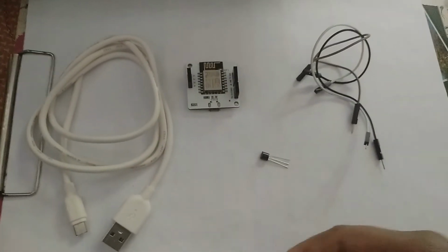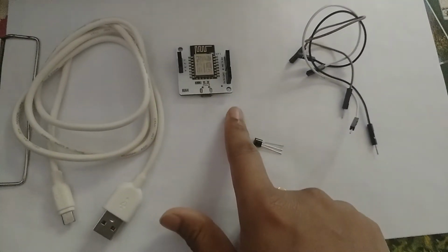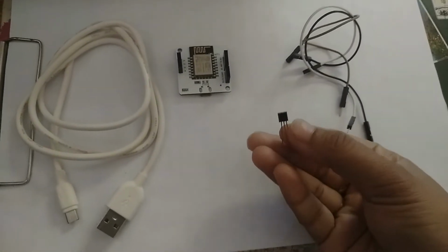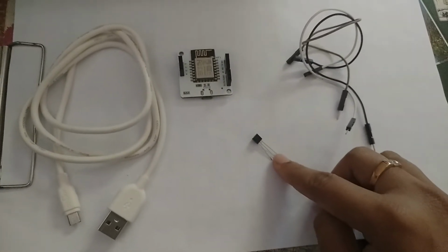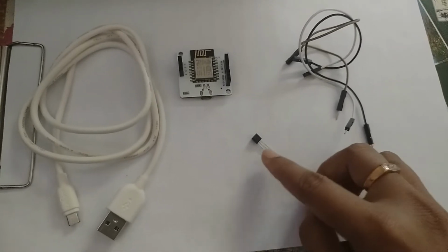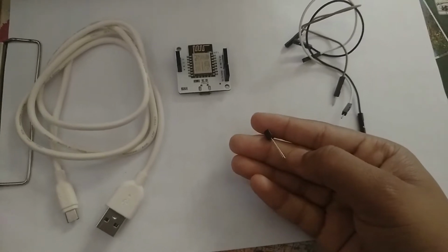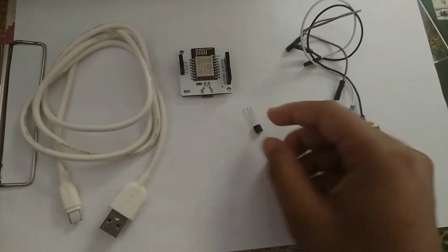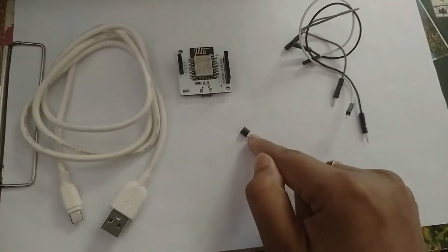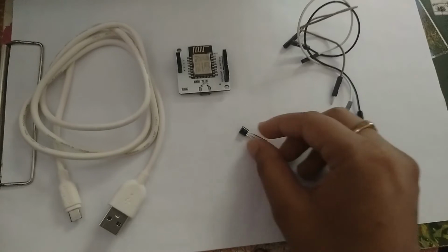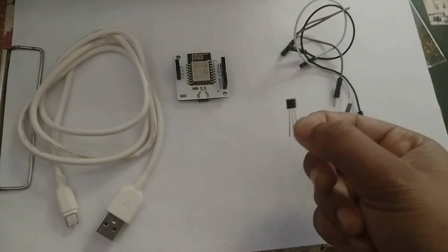So let's go to the connections. What hardware do we need? A USB cable, the Bolt Wi-Fi module, and the LM35, which has 3 pins. One is VCC, connected to 5 volts, and the middle one is the output. The output from the LM35 is a voltage. If we want to convert it into Celsius, we can use the formula: temperature equals sensor value times 100 divided by 1024.